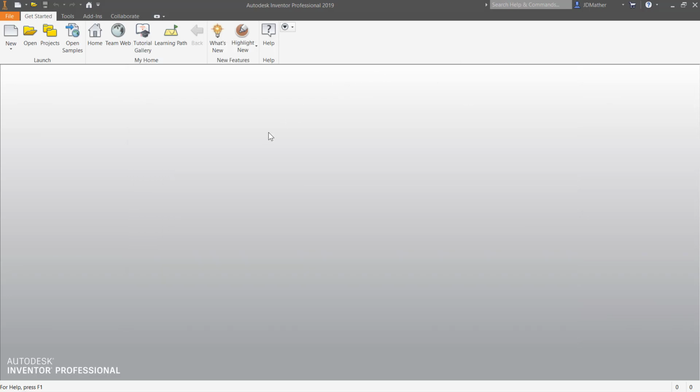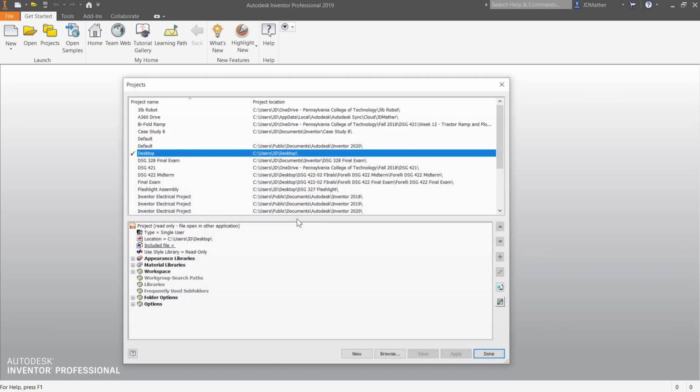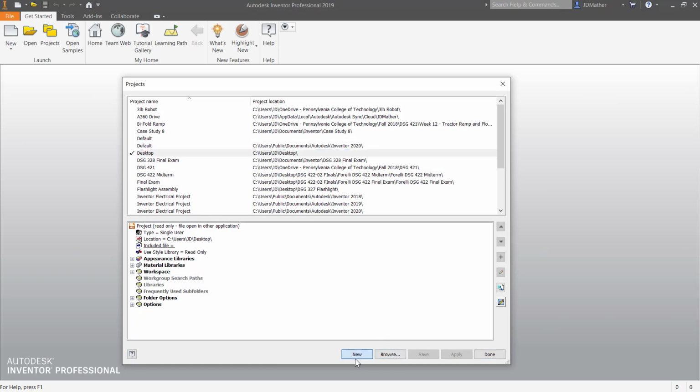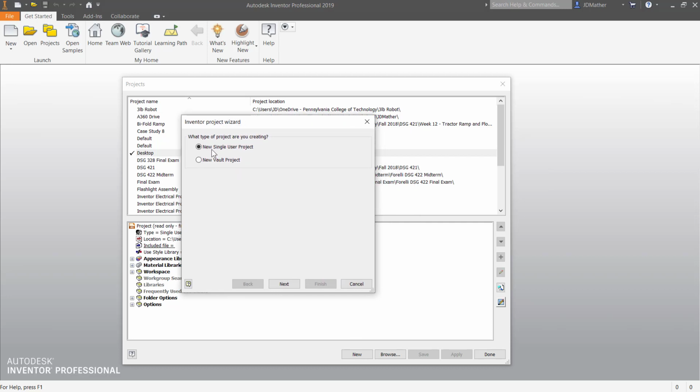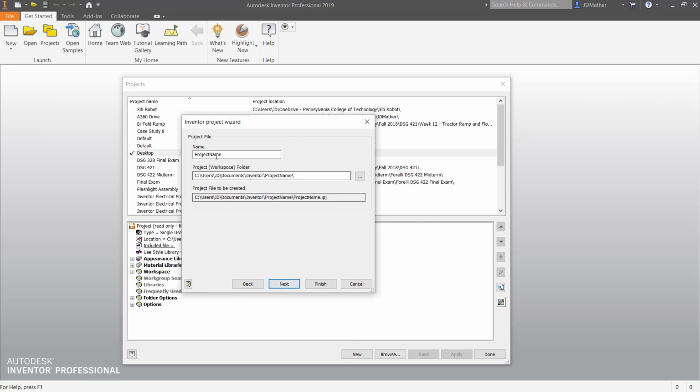I put it in a particular location. Once I have created that project folder, I need to create a project pointing to that folder. So I will go to projects, and I'll say create a new project. I'm assuming that we're not using Vault in this case, so I'll do a single user project, and I'm going to give this project the same name. I'll call it welding shelf, and I'll then click on this...